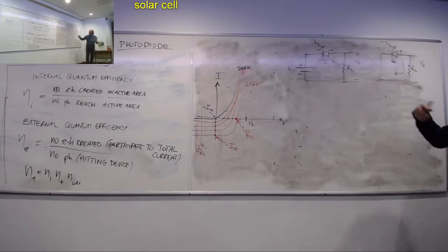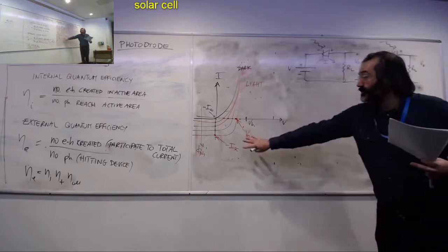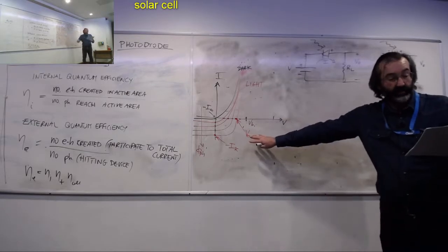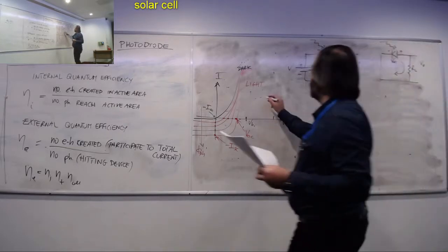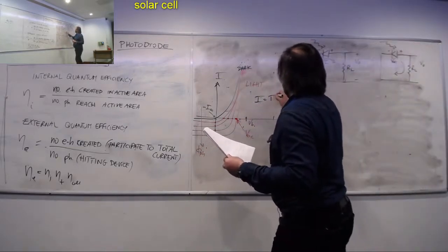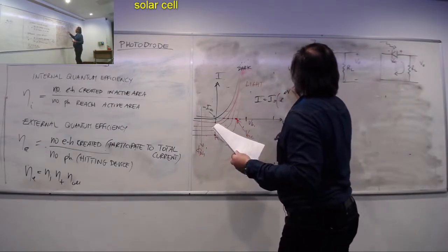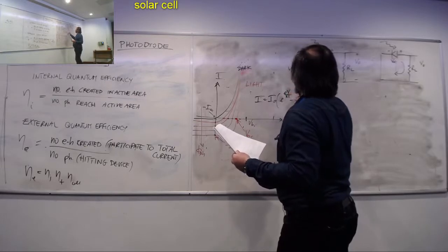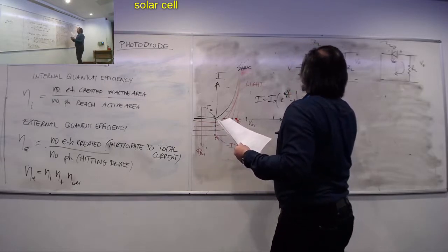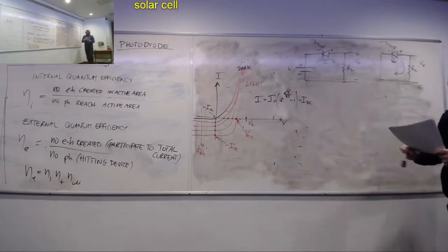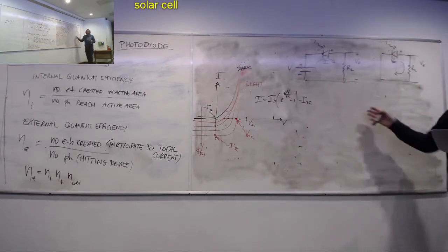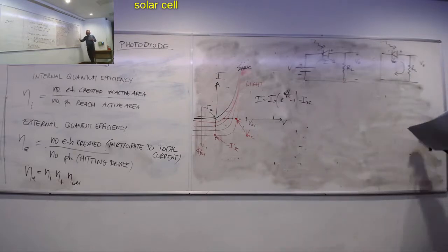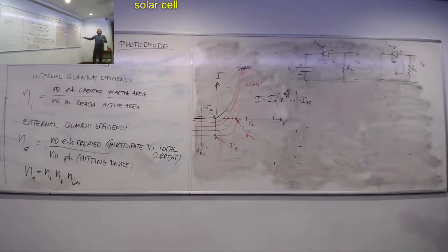So this holds also for the solar cell, and we have our characteristic that was this one here: I0 (e^(eV/kT) − 1) − ISC. And we said previously ISC is related to eta, E, and so on and so forth, and that is the formula we found.